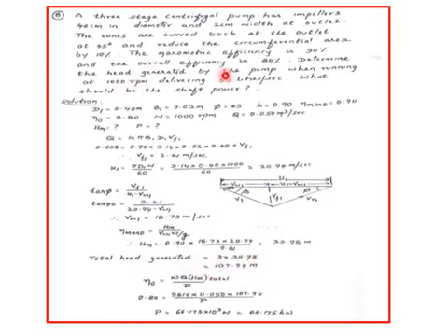In order to calculate overall efficiency, you have to make use of the total head generated, because it is a three-stage centrifugal pump, which is a multi-stage pump. So when you write overall efficiency, it is rho g Q times total head, not the head of one stage. If you take one, it will go wrong, because to drive this three-stage pump we require more power.